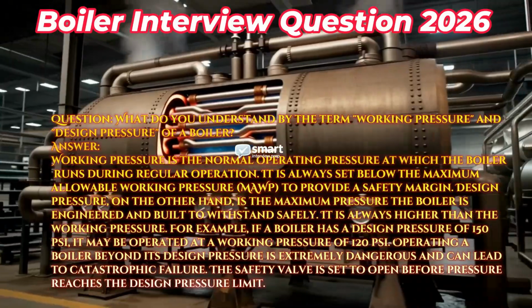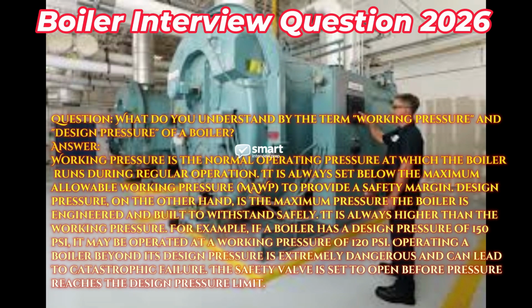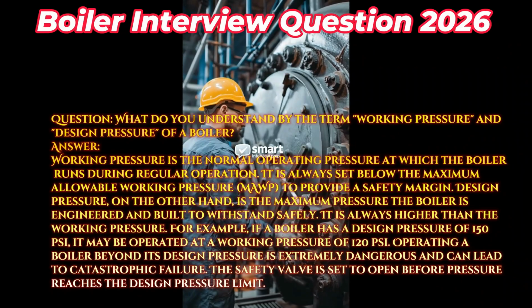For example, if a boiler has a design pressure of 150 psi, it may be operated at a working pressure of 120 psi. Operating a boiler beyond its design pressure is extremely dangerous and can lead to catastrophic failure. The safety valve is set to open before pressure reaches the design pressure limit.